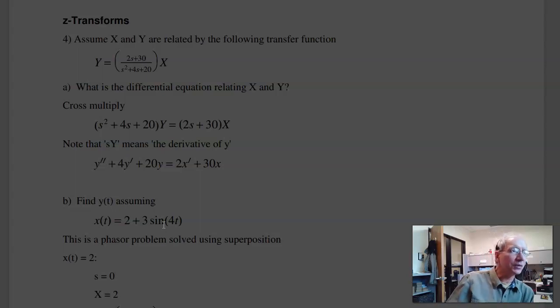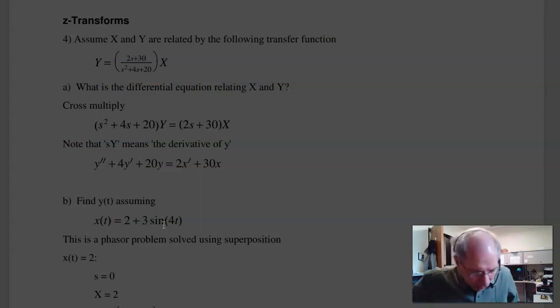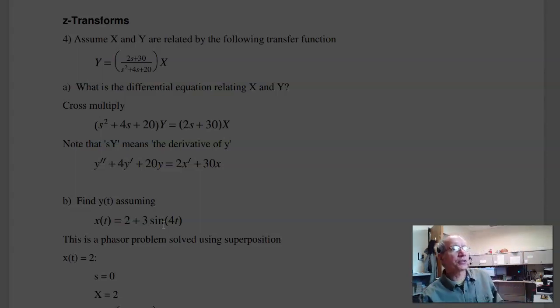So switching gears. The next topic we're looking at are digital filters. With a microprocessor, you actually should be using the Z-transform. The Laplace transform is designed for the continuous domain. Think capacitors, inductors, where you're satisfying differential equations. The Z-transform is for difference equations.